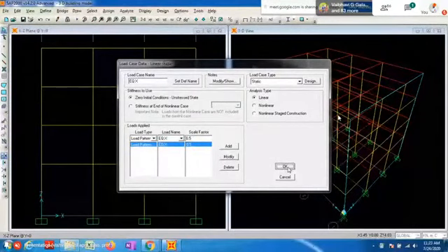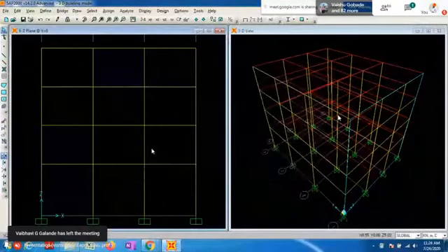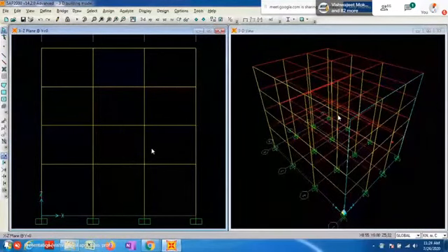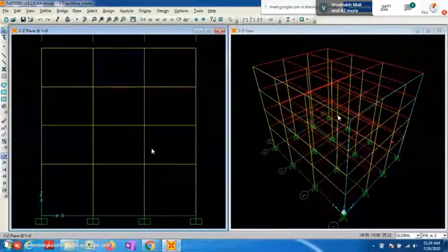Then the building is designed. Some column failures have been shown. Then the sections have been revised once again, and the final sections I am getting are a beam section of 230 by 300, which is sufficient. Then the column section is 300 by 750, because the building is in a severe seismic zone, 750 mm. Concrete is M25 and Fe 415. Okay, so those are the changes.